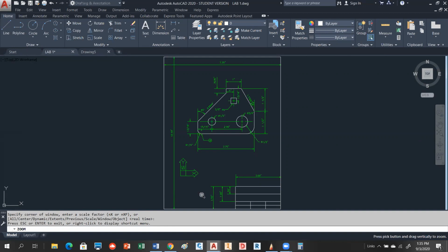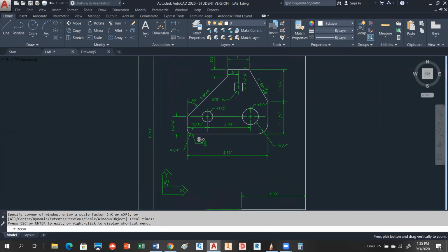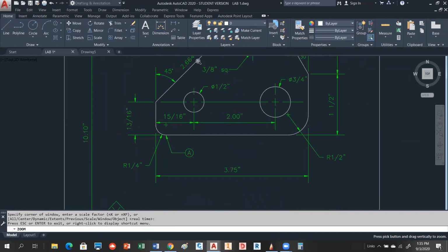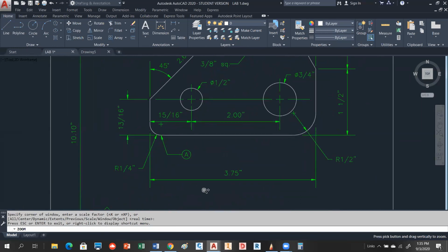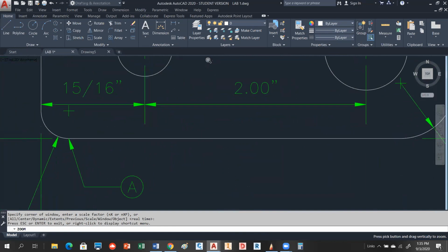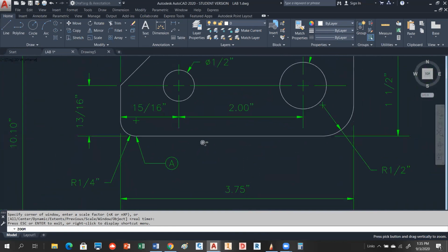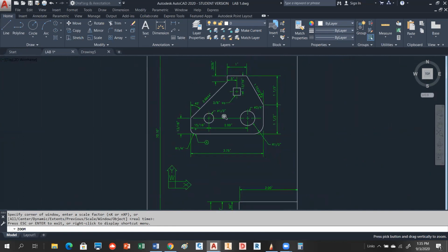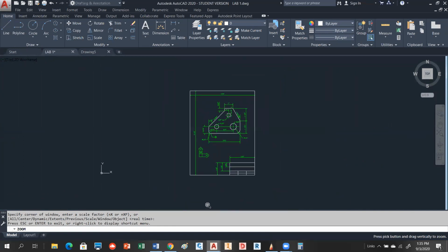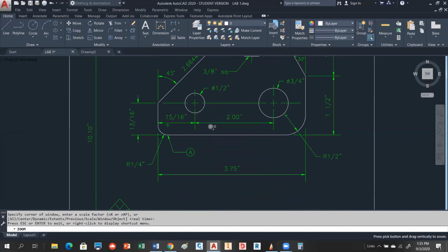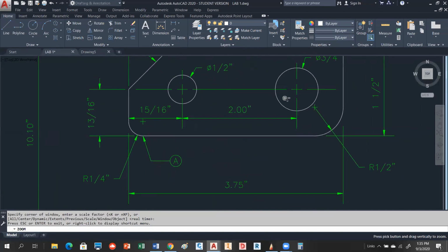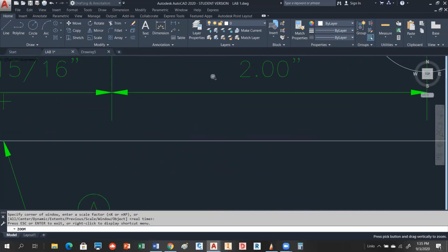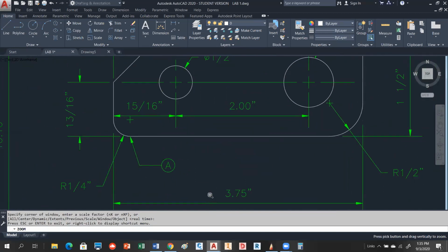If you want to zoom in, you take the magnifying glass to the bottom of the screen, you left click, you drag while you're holding it, and then you release, okay? So from the bottom to the top is a zoom in. From the top to the bottom is a zoom out, okay? So we're doing this in real time. Real time zoom out, real time zoom in. Left to right does nothing, okay? So it's only top to bottom, bottom to top, okay?